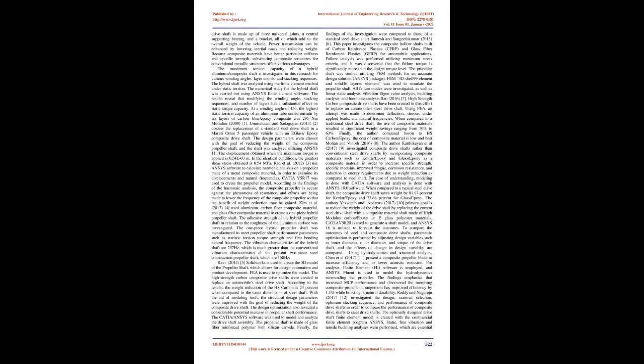Rao et al., 2012, used Ansys software to calculate harmonic analysis on a propeller made of a metal composite material, in order to examine its displacements and natural frequencies. Catia V5R17 was used to create the propeller model. According to the findings of the harmonic analysis, the composite propeller is secure against the phenomena of resonance, and efforts are being made to lower the frequency of the composite propeller so that the benefit of weight reduction may be gained.